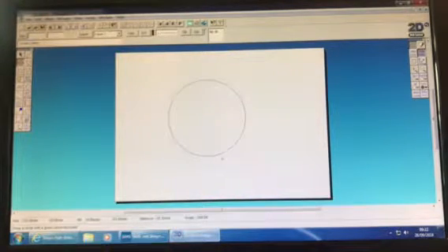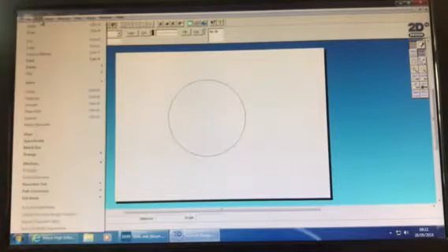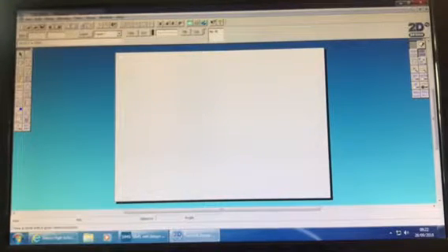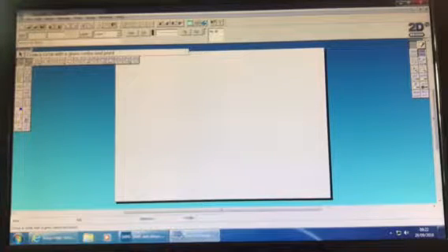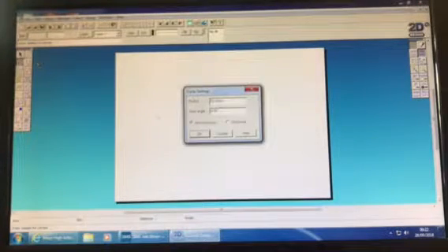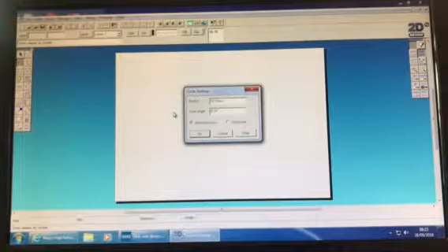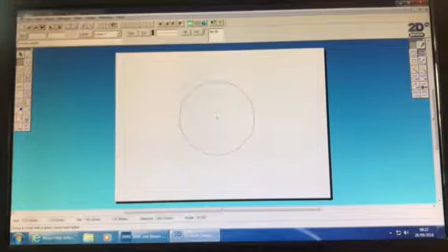There, I've drawn a circle, but unfortunately I'm not sure how big I've drawn that circle. I'd have to count all the dots in between to see. A better way to do this would be to go to the circle, click and hold, scroll out and pick up radius. Now our clocks are going to be 150 millimetres, so half of 150 millimetres is 75. If I change the radius to 75 now and don't change anything else and click OK, this gives me the size of clock.